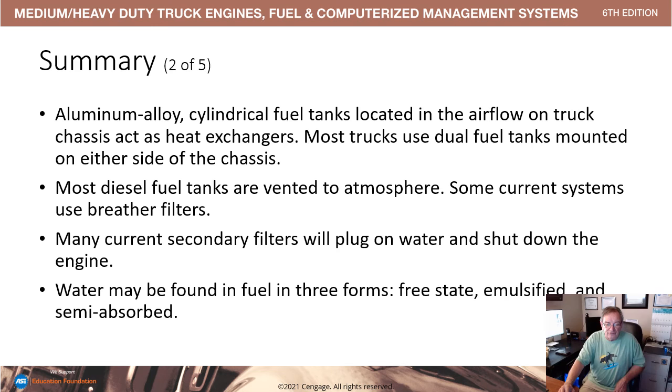Aluminum alloy cylindrical fuel tanks located in the airflow on a truck act as heat exchangers. Most trucks use dual fuel tanks mounted on both sides of the chassis. Most diesel fuel tanks are vented to the atmosphere. Many current secondary fuel filters will plug on water and shut down the engine. That is the content of several test questions.